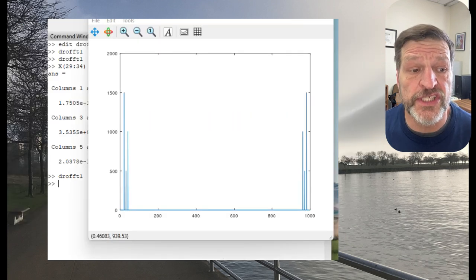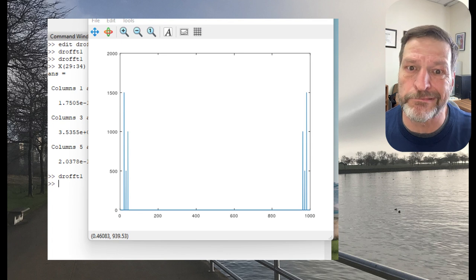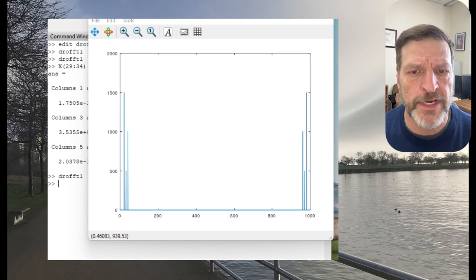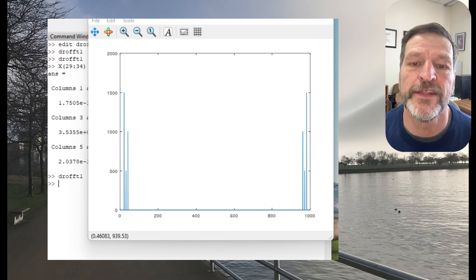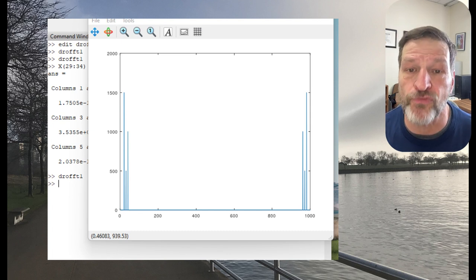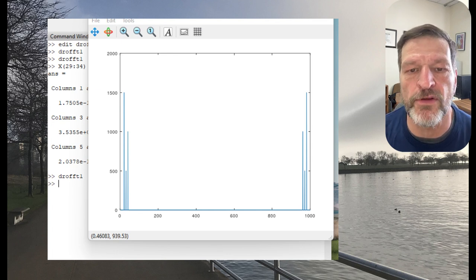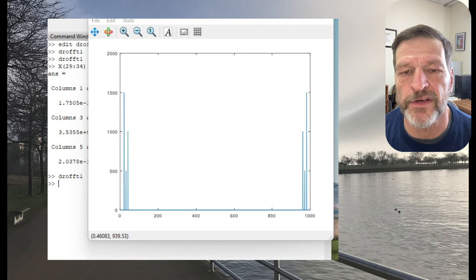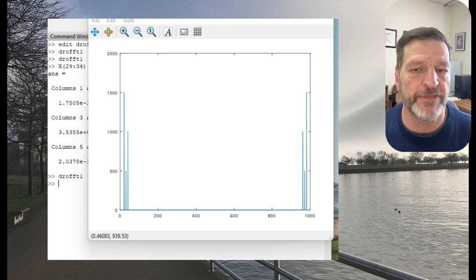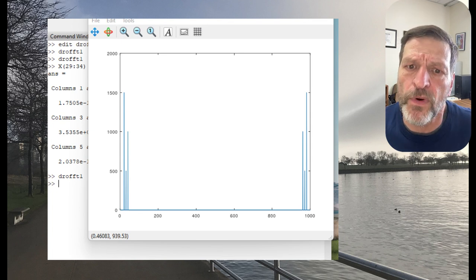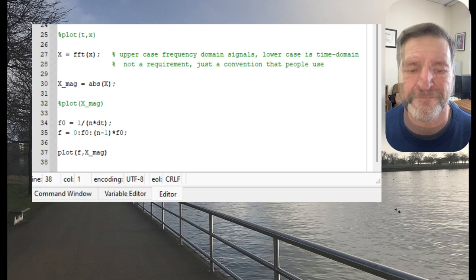And when you see that, you can see there's three numbers. They're big, though. The y-axis is huge, but you see three numbers, and then you see at the other end, on the right side of the graph, you see three more numbers. This is what we all know and we're all predicting is wraparound, right? So around the middle frequency there, the 500th point of these 1,000 points in this file, the data is going to be wrapped around that center frequency, and so you're going to see that. So we do. That's comforting. That's good. But what we need to do is we need to make the x-axis right, and we need to make the y-axis right. So that's the next step.